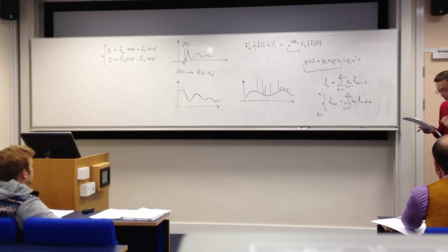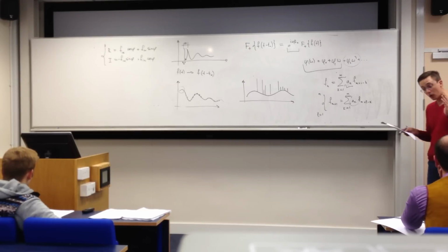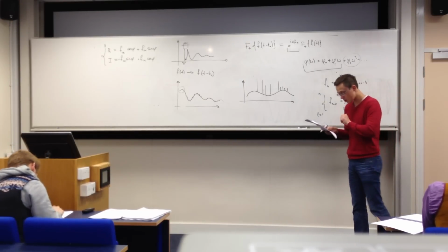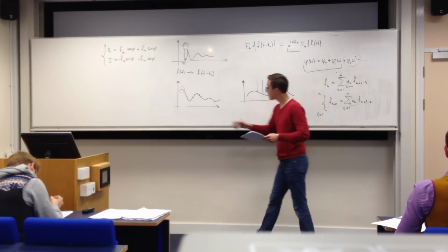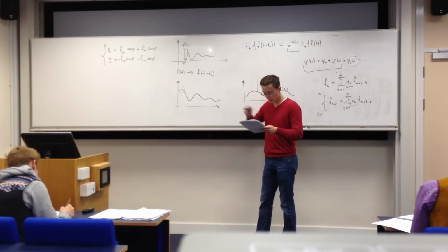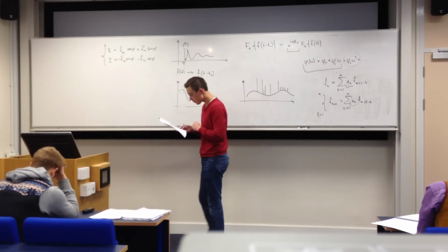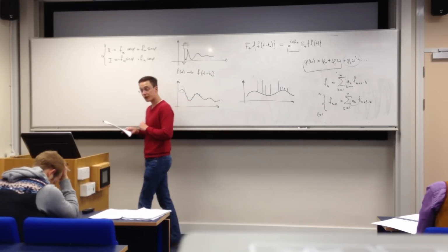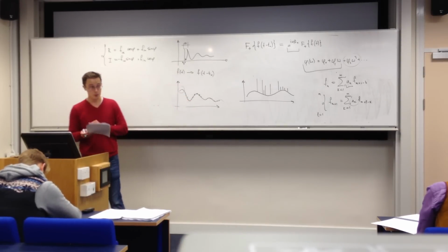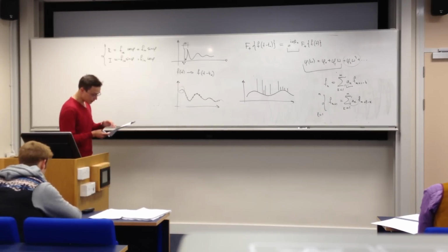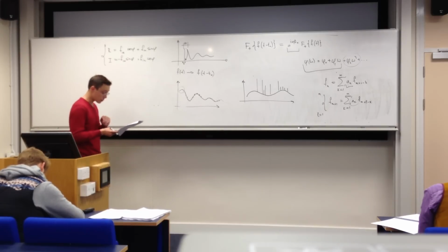And figure 5 in the handout gives an example of forward linear prediction. It's a single sinusoid for the basis for the training, with a bit of Gaussian random noise added to it in MATLAB. And then MATLAB simply has a function that performs linear prediction. A one-line command reconstructs the rest of the signal all the way to the decay.